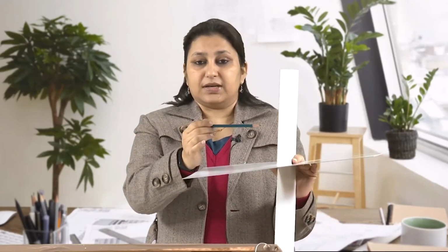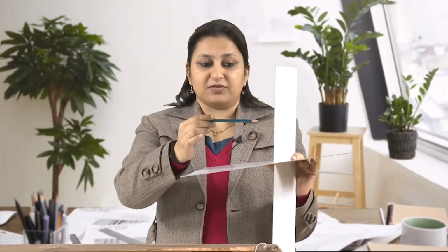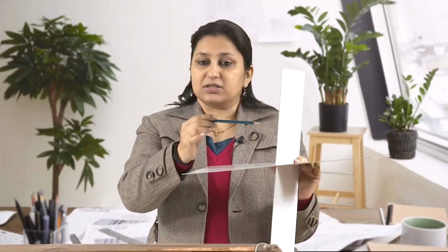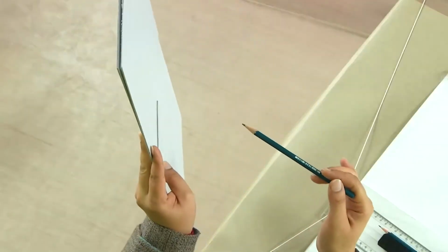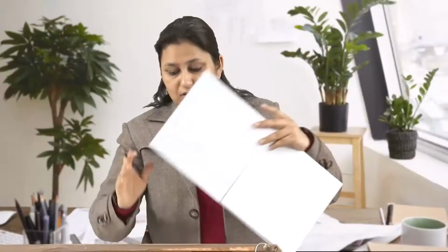So, if you remember again, this is how we understood the quadrants: first quadrant, second quadrant, third quadrant and fourth quadrant. Now just imagine that I have this pencil and the tip of this pencil is actually the point which we are considering. Suppose I place this point at some distance from VP, say 5 centimeters from VP and 7 centimeters from HP, which is the horizontal plane. I will start to draw the projections on a flat sheet of paper like this. So let us see how it looks when we draw it on the sheet and how we draw.